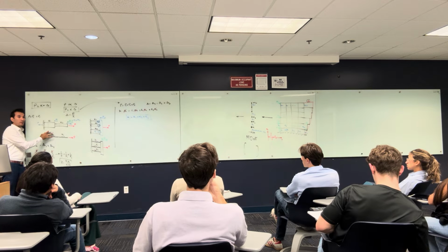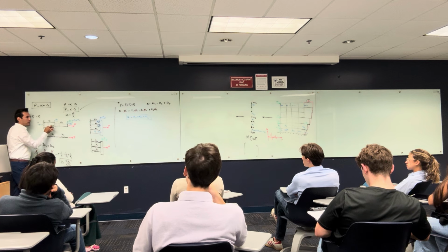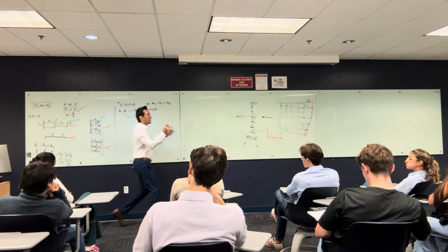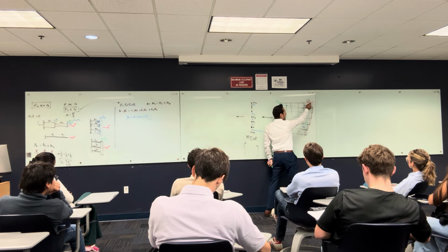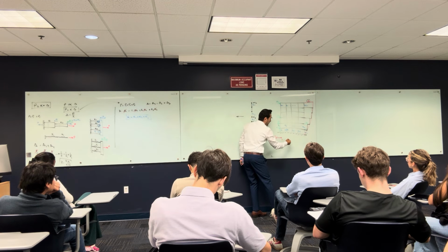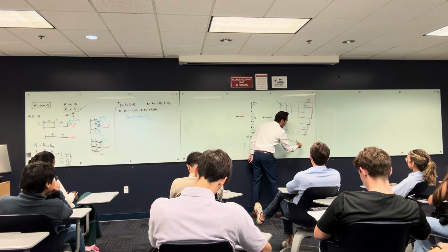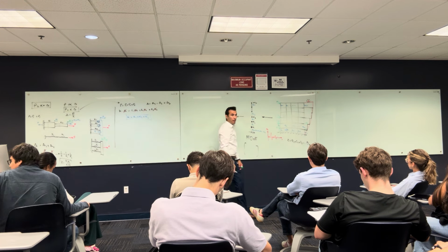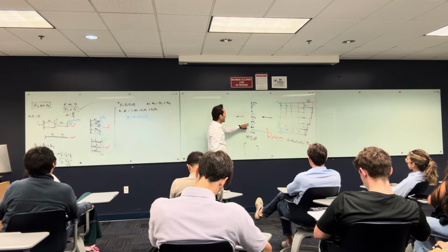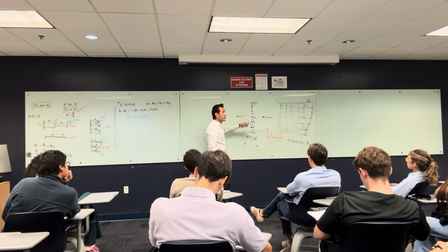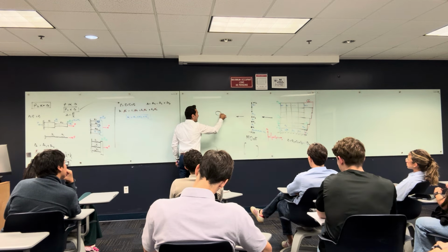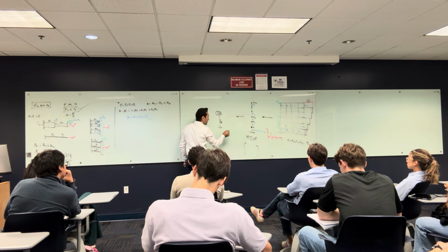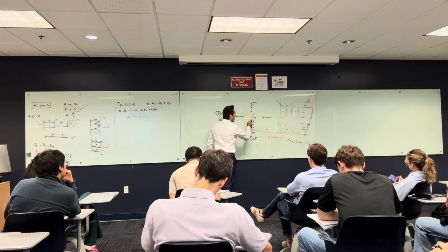This is stiffness in series. Because you have the stiffness from story 1 contributing delta 1, and then this contributing delta 2, and delta 3 and delta 4, and at the end the summation of all these deltas is going to be equal to the total drift, because delta is equal to drift 1 plus drift 2 plus drift 3 until drift n, right? So you can say that the stories are in series. So you can sum all these stiffnesses and get one single mass and one single stiffness that can represent this structure, and this stiffness is the series equivalent of all these stiffnesses.